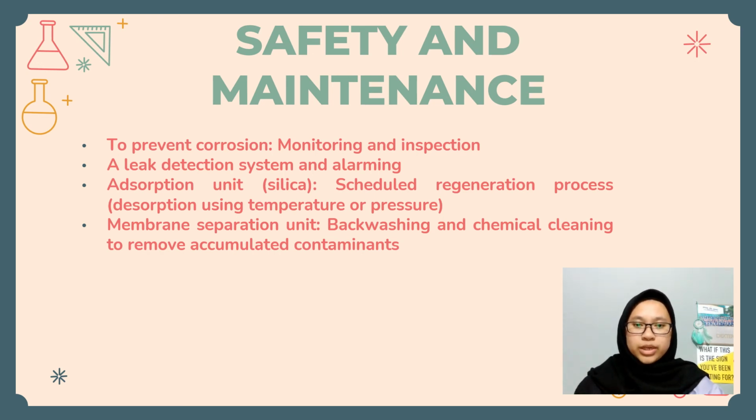Also, frequent and scheduled regeneration process is needed to ensure an optimum operational life of the adsorbents. Last but not least, backwashing and chemical cleaning of membrane separation is needed to remove accumulated contaminants in the system.